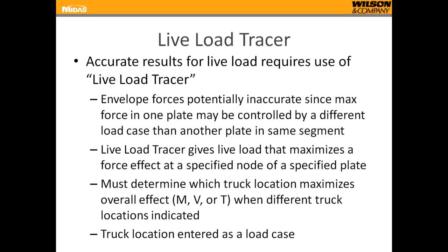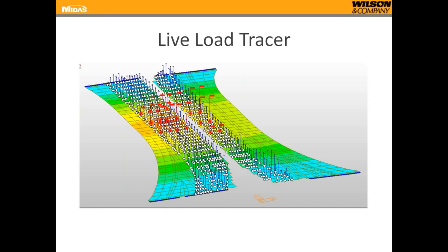Like I was saying, there's multiple plates that went into determining the moments in this structure. So part of the process was determining which truck location maximizes the overall effect, the shear, moment or torsion, when different truck locations are indicated for a single element. The truck location that was given using this tool was then entered as a load case.